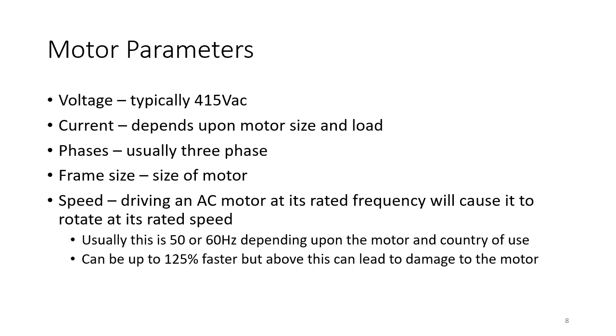And of course, when the motor is running at full speed, it will run at full current. Phases, usually there are 3 phases. This gives us the most efficiency of the motor without having to need very large conductor sizes inside the motor. Frame size, that's the actual size of the motor, and there are standardized frame sizes for particular applications.